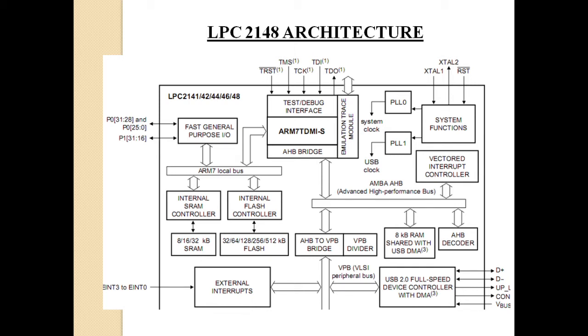Then after a few years, what is the problem here? You need to have a separate UV eraser for erasing the program, and it will take around 20 minutes for erasing that EPROM. And since UV is a heat radiation, maximum you can perform only 1000 erase cycles. An external additional eraser is required, and 20 minutes it will take.